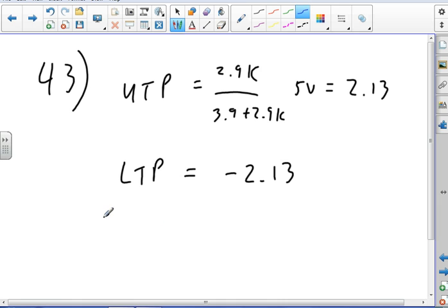How much current does it take to turn on a light emitting diode? And the answer is 15 milliamps, right? How does that compare to 5 minus 0.7 divided by 2.2K? Because the maximum current through RC is going to be that.